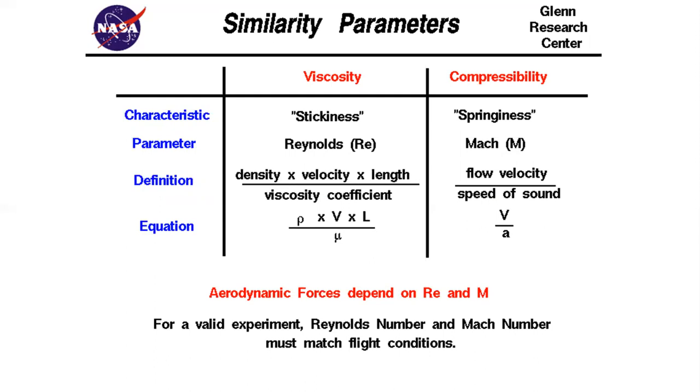This factor is related to flow separation, and so on, and related to the maximum lift coefficient of the aircraft. Viscosity, Reynolds number, compressibility, Mach number. And for a valid experiment, you must tailor your Reynolds number and Mach number in the wind tunnel to the flight condition.